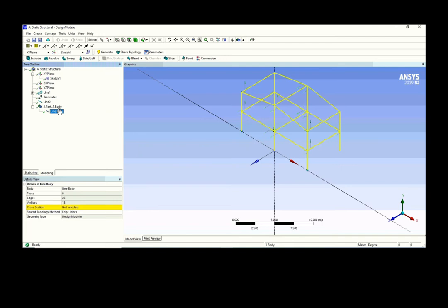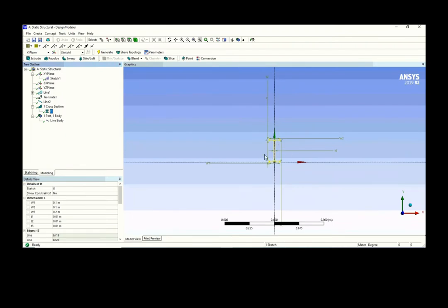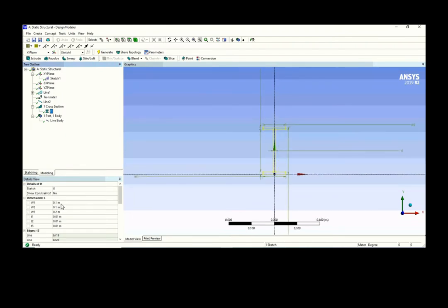So next will be putting in the cross sections. You will see there is a yellow box here: cross section is not selected. So what we need to do is assign a cross section to all these particular line models. So here we go to Cross Section, then we have these I sections. If you click on this, then we have to determine the dimensions of this I. So follow the tutorial as well as the question itself. Then your W1 is 0.1715. W2 also is 0.1715.